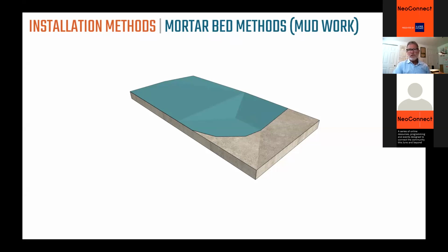You can have sound isolation membranes or sound reduction membranes if you're working with multifamily or hotels, where sound is an issue. And the other one is crack isolation membranes, if you're trying to prevent cracks in the substrate from telegraphing through to the finish. So there are many different kinds of membranes, and today you can get one membrane to take care of all those. I'm not going to give you any manufacturer names, but talk to the folks who make the membranes, which are the same folks that make the thin set and the grouts in many cases, and they'll tell you all about their membranes.